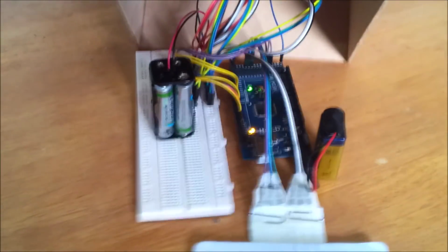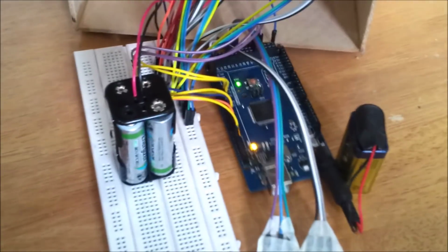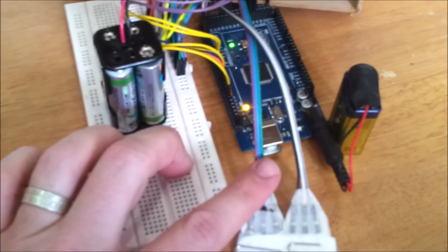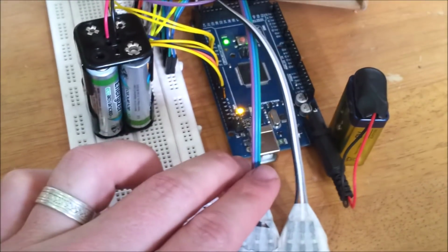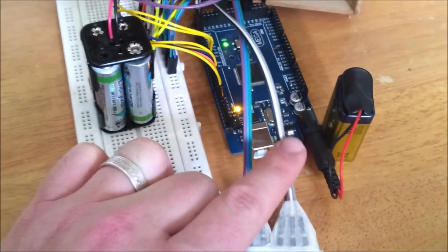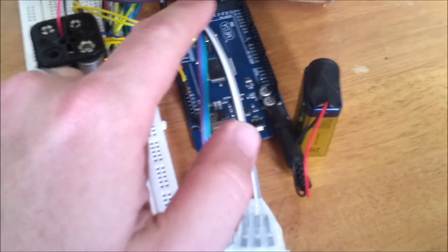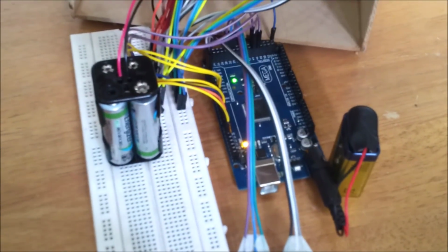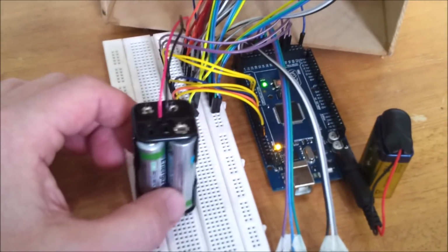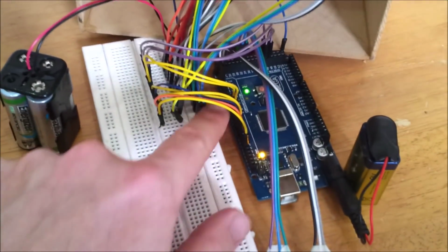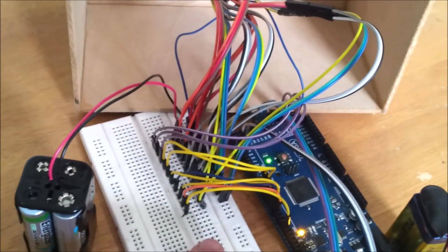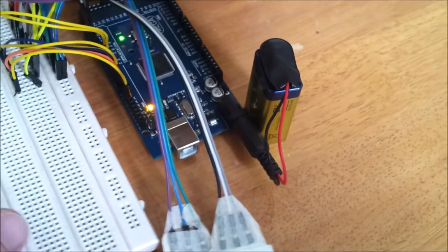Underneath the box we have all the internals, all the electronics. Firstly, the column pins as they come out of the Arduino, they are set as output pins in the program, so they are cycled on and off. The row pins head into pins 19, 20 and 21 of the int0 to int2 interrupt handlers. Got our 4 AA batteries for power, pin outs to control the servos, come onto the breadboard. The breadboard's there for distributing power to the servos. And of course the 9-volt battery which runs the Arduino.